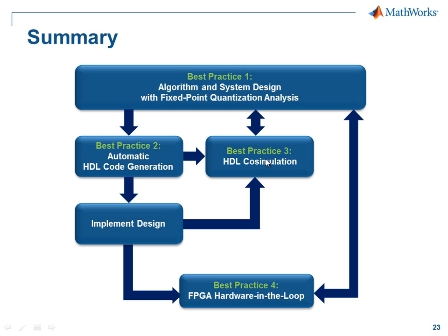With the third best practice, we have reused the system level test bench to verify the generated HDL code by using HDL Verifier, which establishes an HDL co-simulation link between Simulink and, in our case, ModelSim.